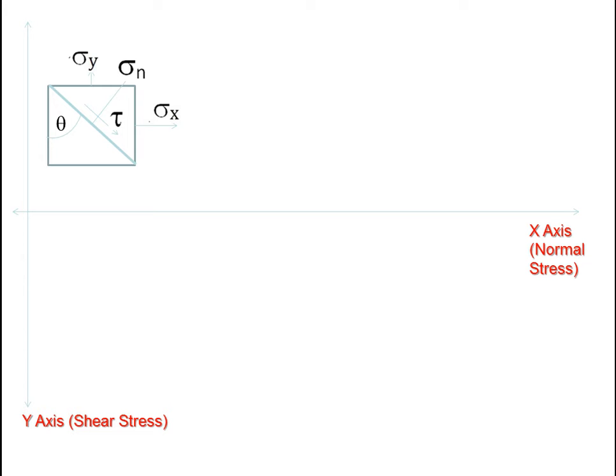So to draw the Mohr circle, we have to mark the vertical plane and horizontal plane in the first step. The vertical plane carries only sigma x and the shear stress is 0. So from the center of the coordinate system, we mark sigma x on the x-axis, after converting the stress value into a suitable coordinate system.